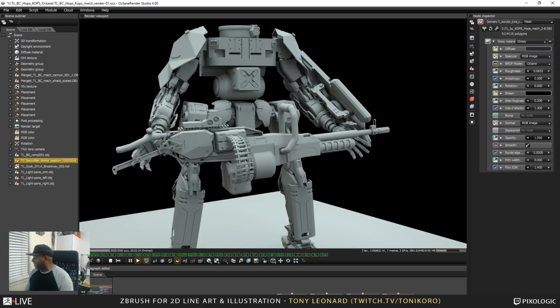But select apply modifiers when exporting. Yeah, you could definitely apply modifiers when exporting. Sometimes I have found, though, every once in a while it doesn't grab all of the modifiers applied to every shape. So just me being worried about it, sometimes I'll go down the list, but a lot of times when you convert it, it will generally compact all of the modifiers and leave you with the mesh that's left over, which is great. But if you want to still keep it live so that you can go back and change, I would probably duplicate the file and then do that, or apply all of the modifiers and then save it out.